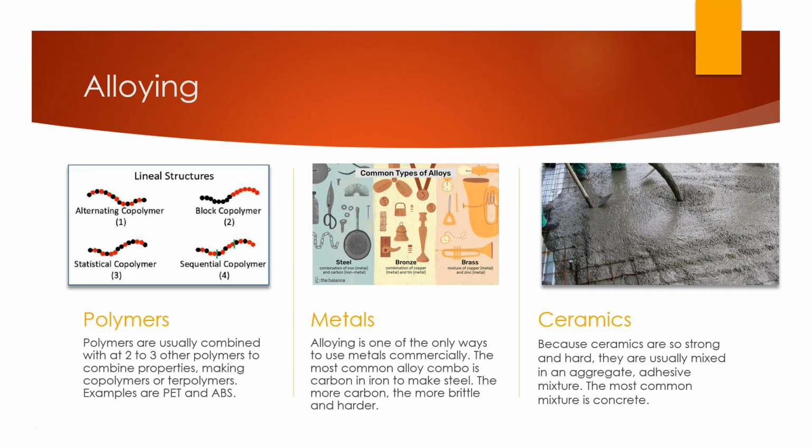This is to get a metal that has the toughness and ductility of iron and the hard, strong characteristics of carbon, the corrosion resistance of chromium, and heat treatment benefits of chromium and molybdenum. Each alloying element is going to have a specific purpose, and the amount of the alloying element added to the major material is very important for getting the properties desired.